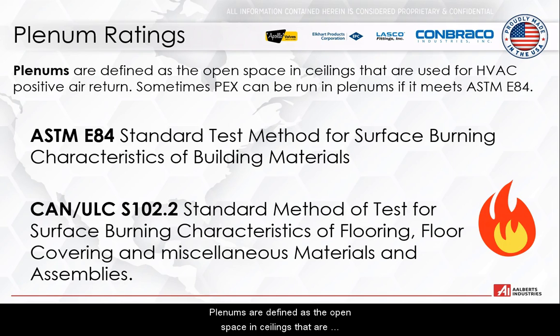Plenums are defined as the open space in ceilings that are used for HVAC air return. Sometimes PEX can be run in plenums if it meets ASTM E84. Most objects, when exposed to heat or flame, immediately begin to smoke. This standard measures a low smoke and burn rating so that the fumes do not enter the HVAC system for a determined period of time. There's also a similar CSA certification.